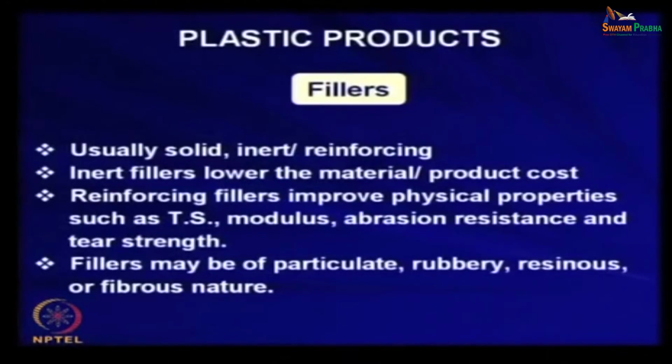And then compressive strength is the load under compression, where deformation also occurs. So, the compressive strength will be high because the stiffness is high if you use an inert filler. That will increase the stiffness and modulus, but it will decrease the tensile strength and the elongation at break. Am I clear? But reinforcing filler, on the contrary, what happens?